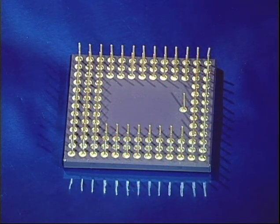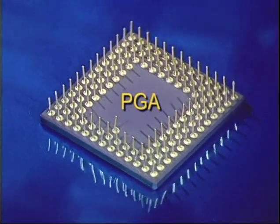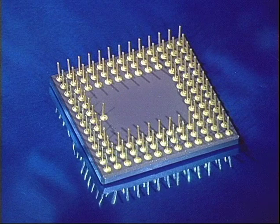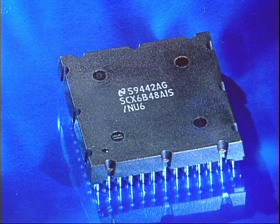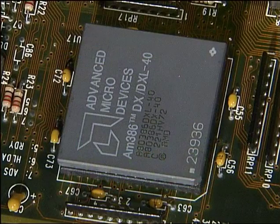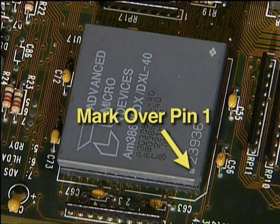Our last through-hole IC is the most complex. Pin grid arrays have several rows of leads extending from the bottom of the IC. The rows make up a grid of connection points. PGAs come in plastic and ceramic packages. For orientation, there is usually a notch or mark directly over pin 1.